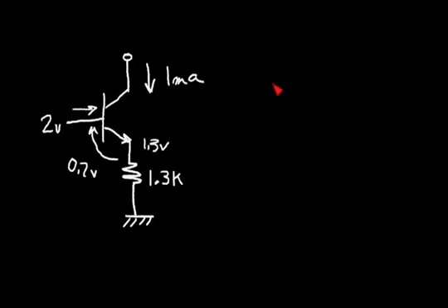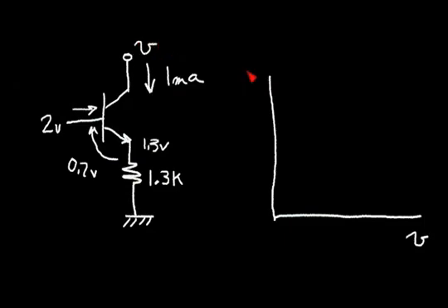Now this current source will be a little less than ideal. Let's plot my current versus voltage, and this is the voltage at the collector terminal and the current in the collector. So the key thing is that the voltage on this current source is limited. Now there's a junction diode in this base collector region that I never ever want to forward bias. So this will act as a fairly decent current source as long as the forward drop on this diode does not cause conduction in this collector to base diode. And so I could go as low as, say, 1.6 volts for the operation of this current source. And that would give me 0.4 volts forward bias of this diode, which may be acceptable.